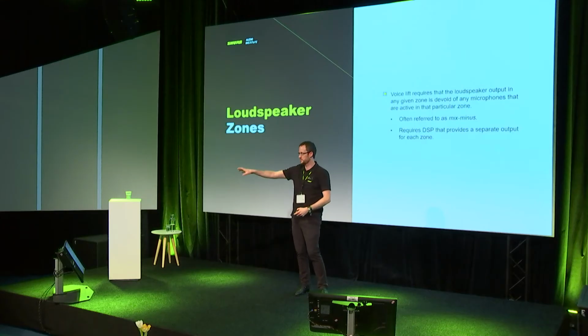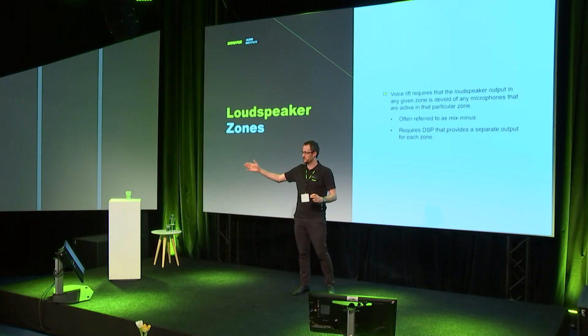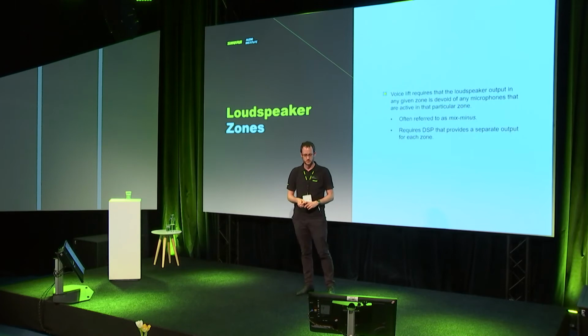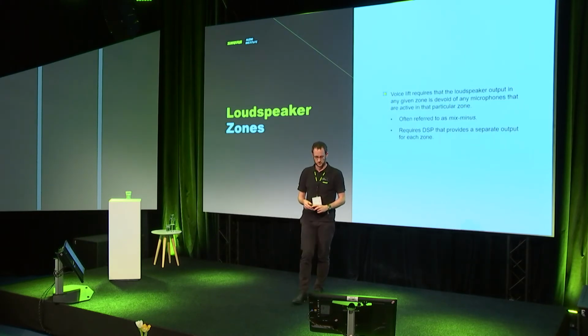Loudspeaker zones become increasingly important when you have a larger voice lift system and a larger number of microphones in it. Because what you want to do is say, right, audio picked up in this specific zone over here is routed only to those specific zones over there. And probably you want to give less loudspeaker reinforcement the closer you get to the actual talker. Okay, and we refer to this as a mix-minus system. So you're putting audio into the ceiling, but not where you're currently producing that audio from.